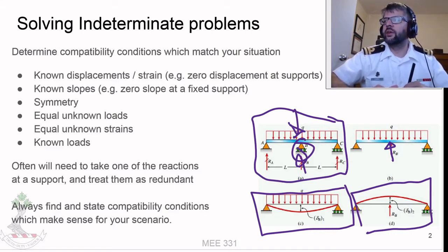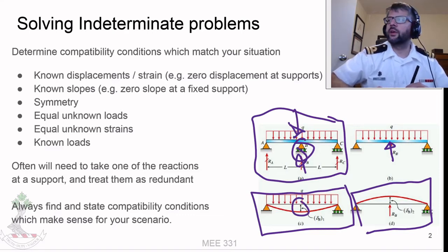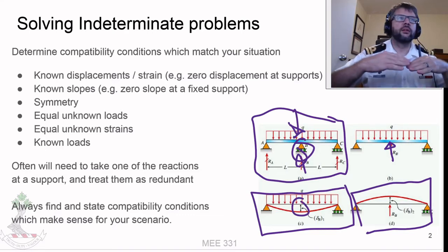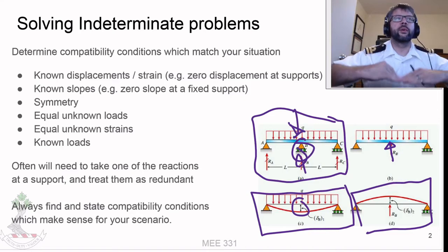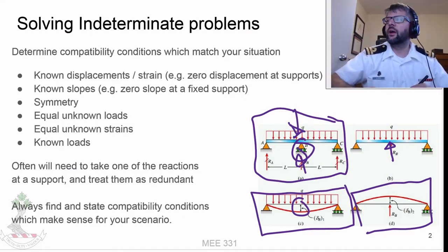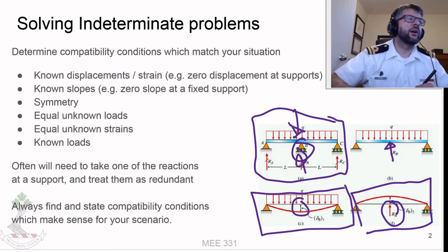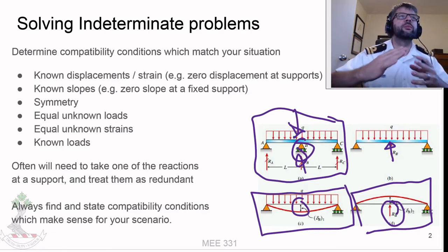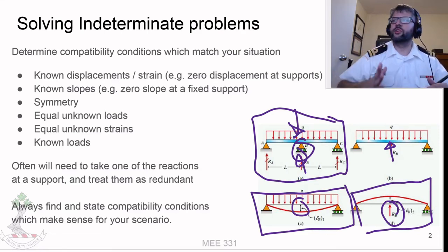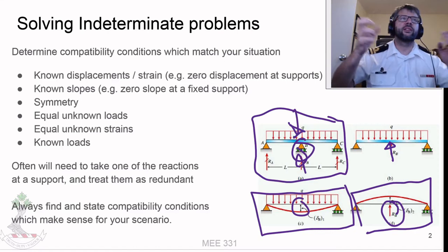So essentially, we take the displacement that would otherwise be caused by the downward displacement from the distributed load, and the force upwards at the reaction needs to be enough that if it was just applied to the beam itself, it would push it up that same amount.